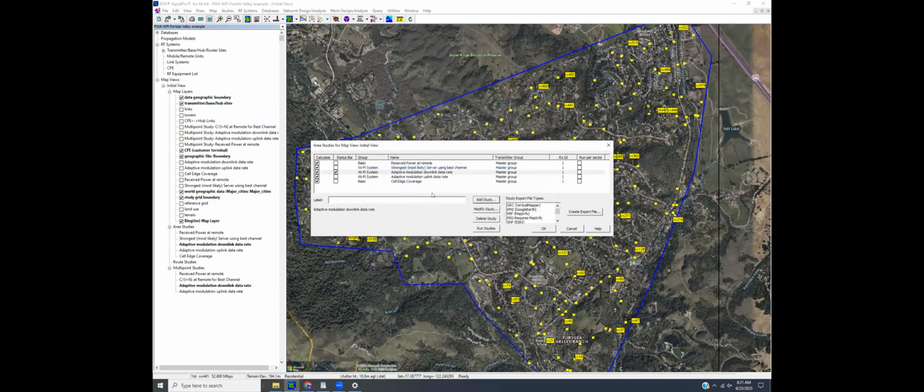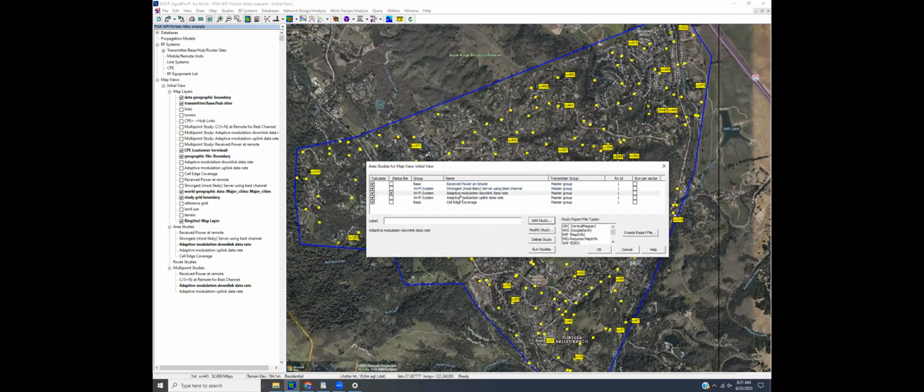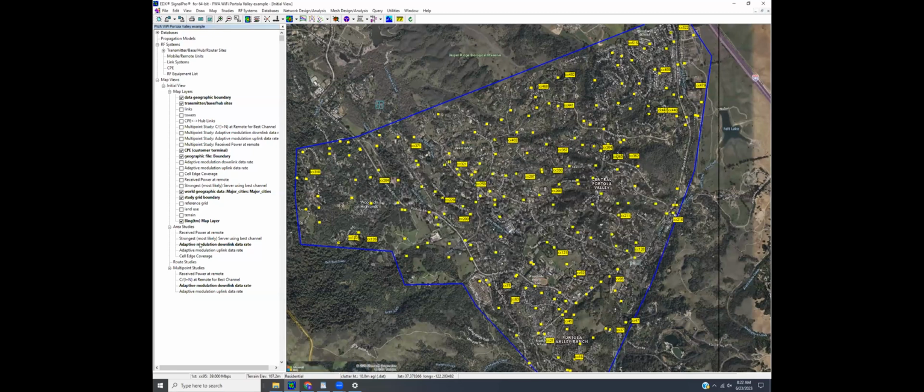And so in this example here, what I did was to go ahead and place my APs using the automatic site placement for multi-point. And then I added my uplink and downlink data rate, my basic cell edge coverage, just to get a pass, no pass, and then my strongest server plot using best channel so that I can see how the channelization scheme would fall out on kind of an area-wide basis.